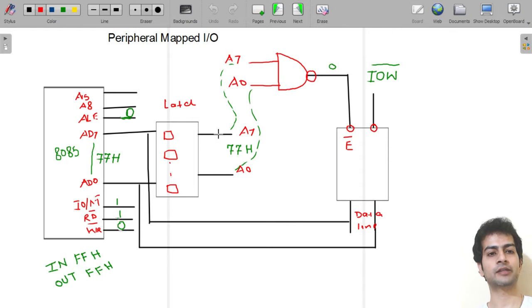I told you that for dealing with the input output device, we require only an 8-bit address, and this 8-bit address gets latched here, and then finally it comes at the lower order address line. So you will say, sir, by this time, what will happen to the higher order address line? Will it remain idle, or what data will be stored there? Yes, the answer is that